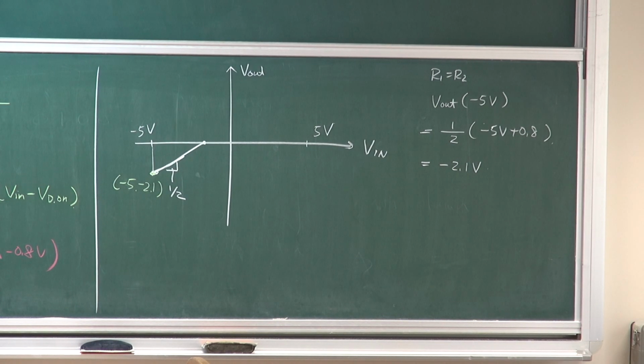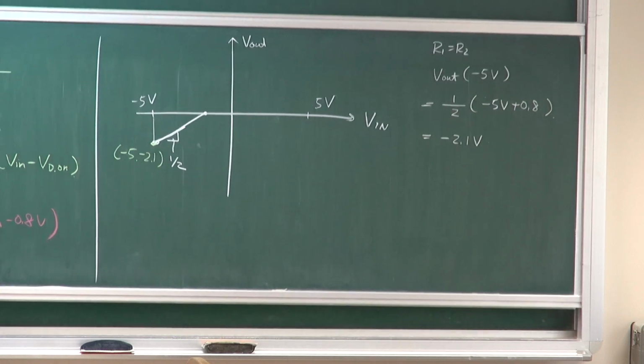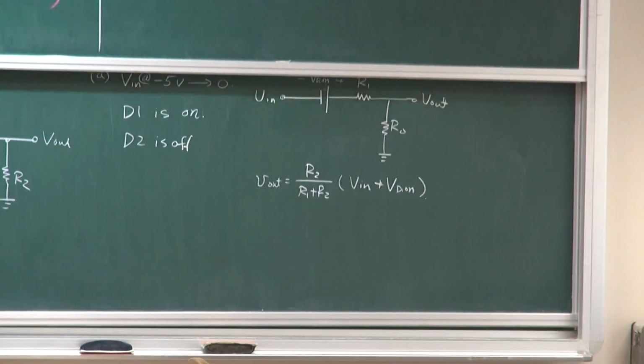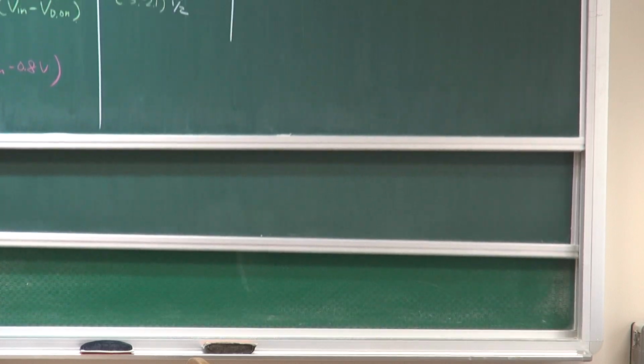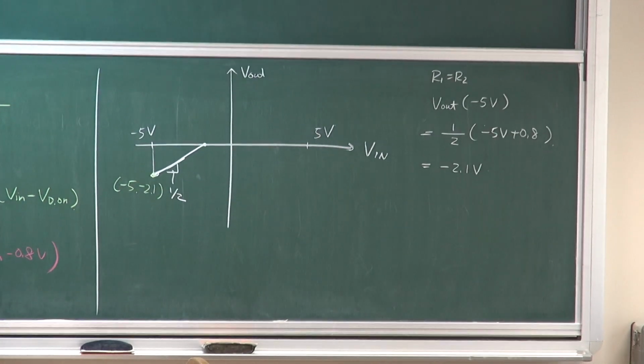If you're looking at the top, simply ignore branch 2. When does it turn off? Well, then you can actually use the equation to do the intersecting. But when does it turn off? Meaning that this diode turns off when there's not enough bias between the two. So this will then lower to 0, and this will be minus 0.8. So this is actually minus VD on.